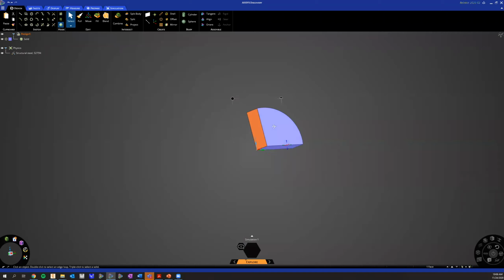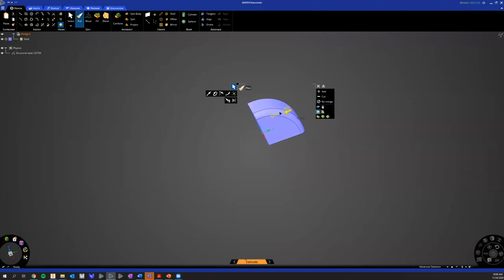That actually works to my benefit because I can quickly make changes to these and there won't be any consequences. What I mean by that is, say I pull this feature and make a radius, I can select this radius and hit the delete key. There are no parent-child relationships like a traditional CAD has, where you might get an error and ruin the parent-child relationships. So that's to my advantage in this program.